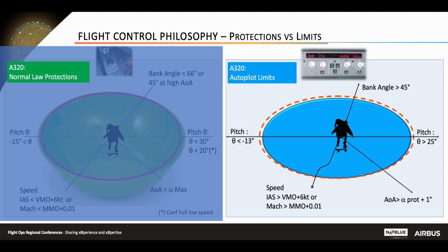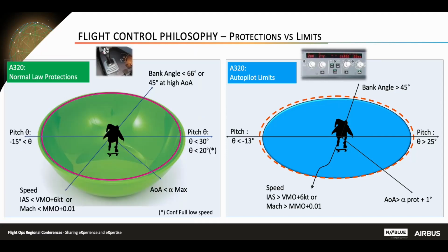As we saw previously, the autopilot can operate with various gains depending on the situation. Nevertheless, the autopilot is not able to cover all the flight domain. This is why, for example, we have some auto-land limitation and the aircraft has to be flown manually above maximum crosswind limitation. So we have reviewed the flight control envelope and its protection, providing the aircraft positive stability versus the autopilot operating area within its own limit.